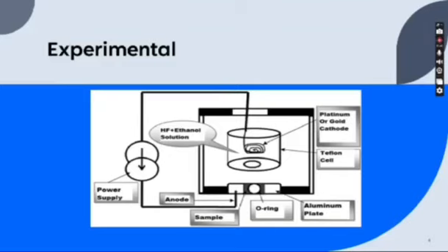The silicon substrate is placed vertically as an anode against a circular hole, offering a surface area of 0.64 cm² in contact with the electrolyte. On the other hand, a circular gold grid was used as the cathode in our electrochemical reactions, as shown in the figure. For porous silicon layers with a diameter of 10 mm, we designed an anodizing bowl with a circular opening.